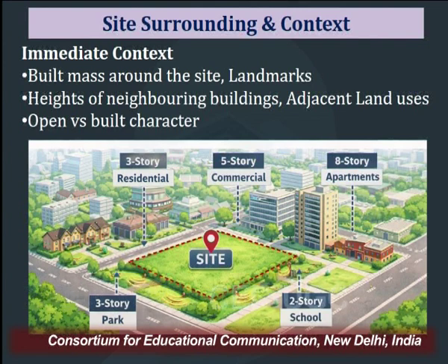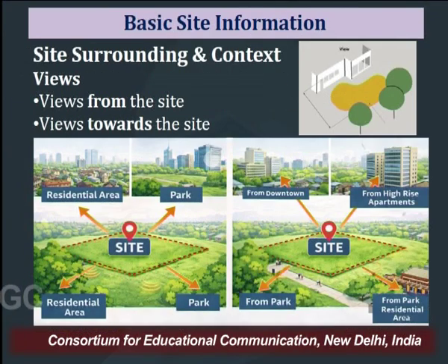What are the landmarks? Is there any major historical building or maybe a religious building around the site? What are the heights of the adjacent land uses, what is the open area around the site? So, all these impact the quality of the site. It helps you to work out the views, the views from the site and the views towards